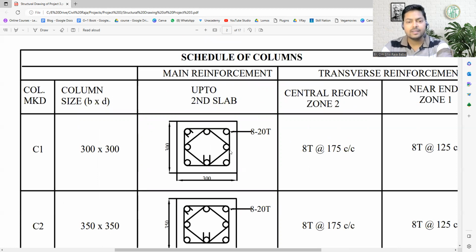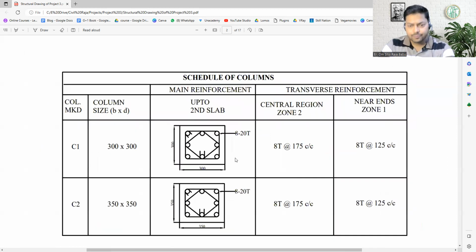Then we have this diamond stirrup also. So this rhombus-like shape is known as a diamond stirrup. Okay, so this is also used when we have 8 bars. When we have 6 bars, then we have a different arrangement of binding them. I will also show that in some different project, but for now we have this particular project and we are talking about this one.